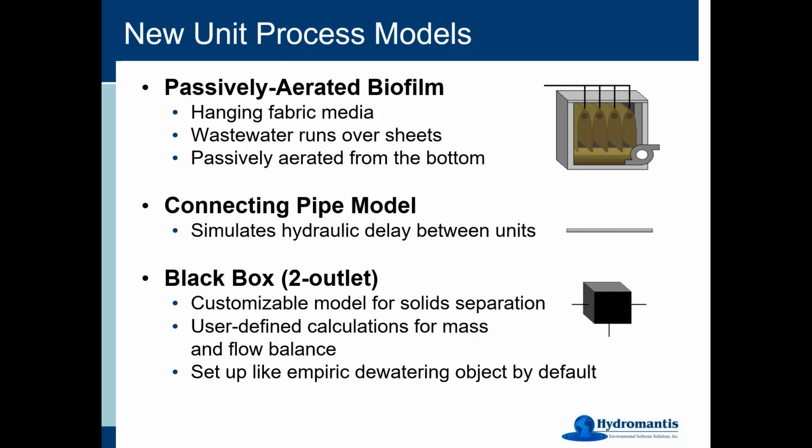The reason it's there, and actually I've had to use it on a couple projects, is just to simulate the hydraulic delay between units on your drawing board. Occasionally, we make the assumption that when it exits one unit, it's pretty much instantaneously arriving in the next one. And that's quite fine for the timescales that we work on for most plants. But occasionally, you might have quite a long delay when it leaves one place and it has to swing around the side and go across the back of the plant or something. And so we now have that there if you need it.